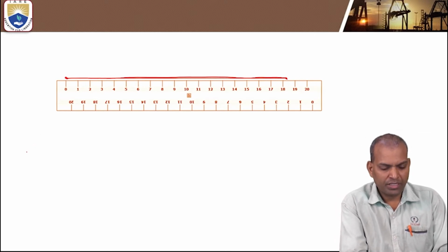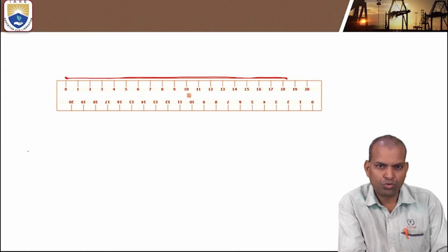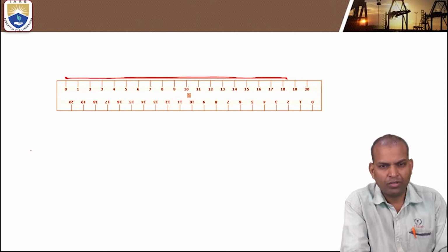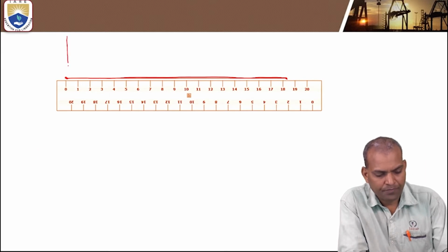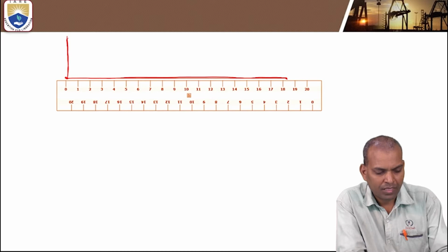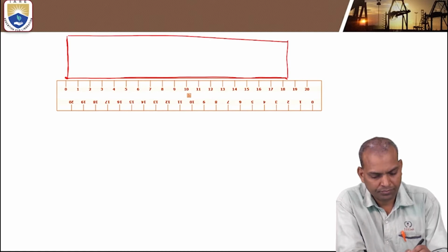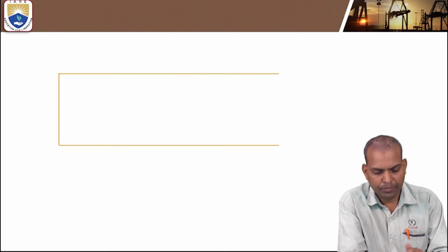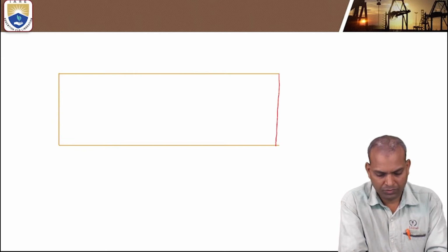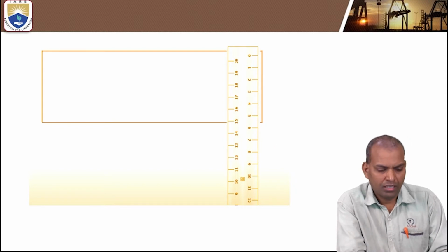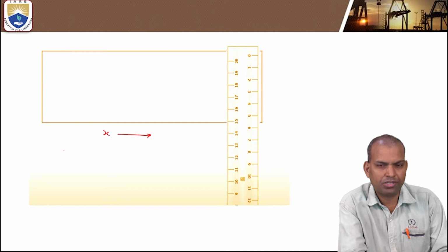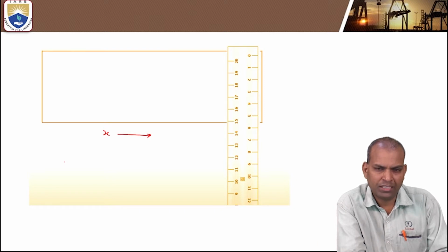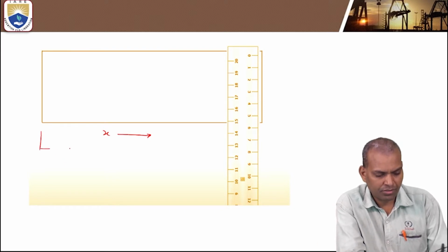After drawing the 18 centimeter line, the x-axis, we draw the y-axis. The y-axis is the length of the lift, or stroke, of the follower, which is 6 centimeters. Draw 6 centimeters in order to complete the rectangle. The x-axis represents the cam rotation, which we converted into a linear scale, 18 centimeters in total.